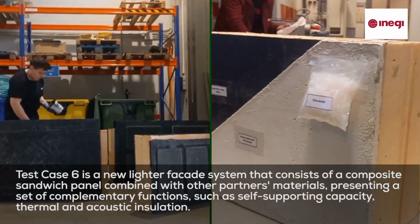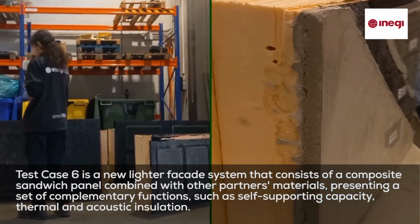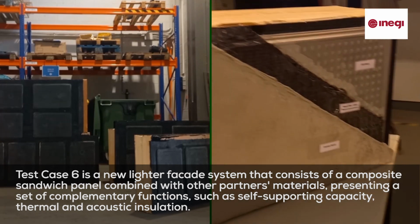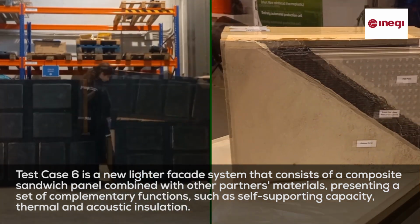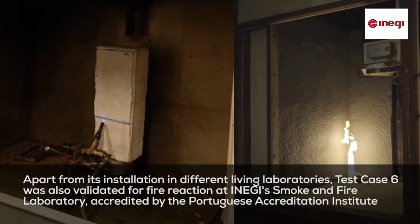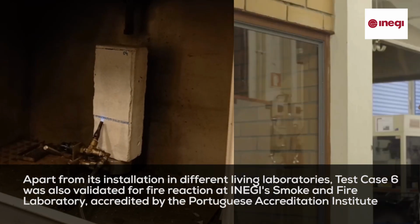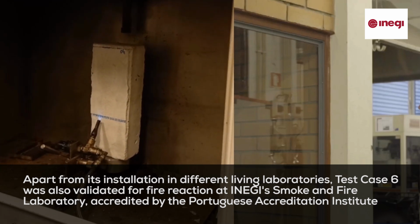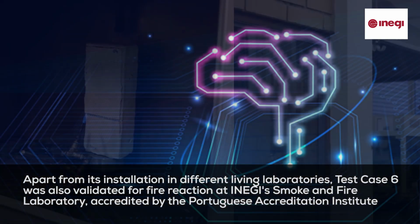Test Case 6 is a new lighter facade system that consists of a composite sandwich panel, combined with other partners' materials, presenting a set of complementary functions, such as self-supporting capacity, thermal and acoustic insulation. Apart from its installation, in different living laboratories, Test Case 6 was also validated for fire reaction, at INEGI's Smoke and Fire Laboratory, accredited by the Portuguese Accreditation Institute.